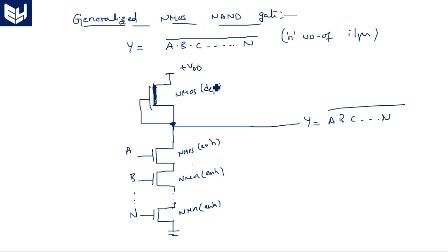So the realization of the NMOS circuit only involves one transistor in the pull up place, and the remaining realization is the same. The bottom part of the CMOS logic circuit is equal to the bottom part of the NMOS logic circuit. Both are the same. I will write that point also.